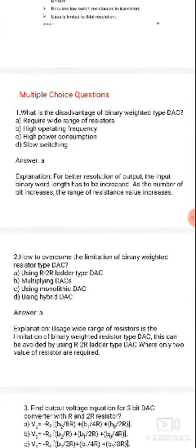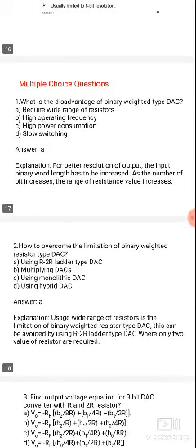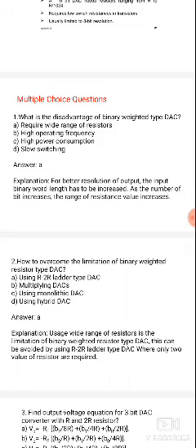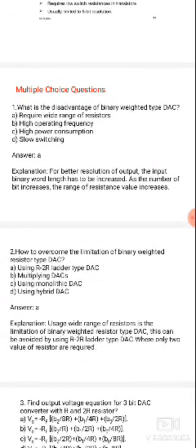These are the 4 important terms that we discussed last time. In digital to analog conversion, the 4 important terms are resolution, monotonicity, accuracy and settling time. Resolution is 1 by 2 power n minus 1, into 100. It is the reciprocal of the number of bits.